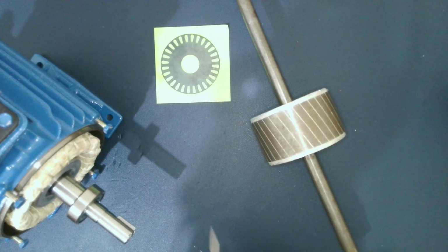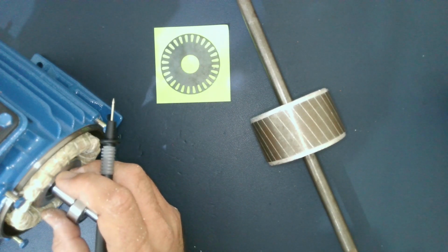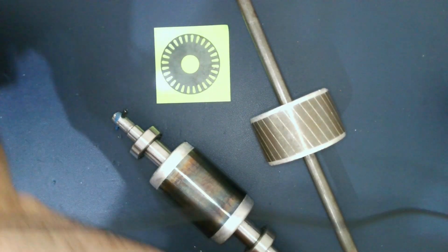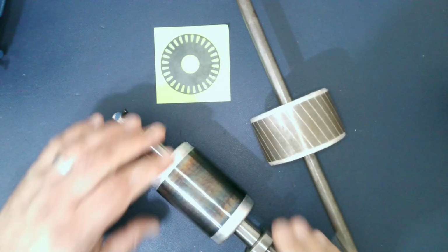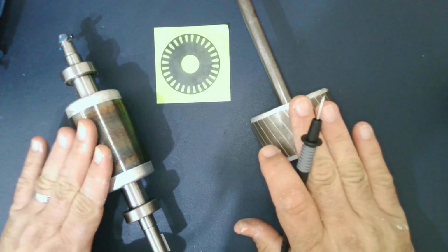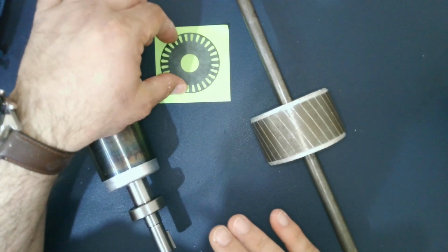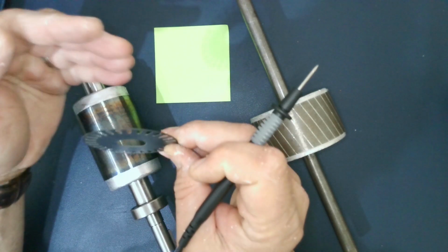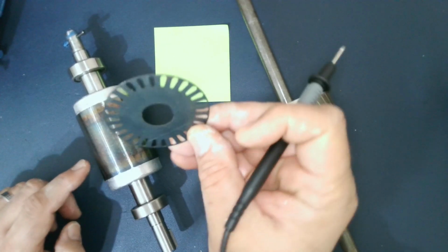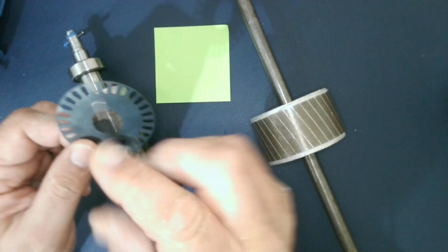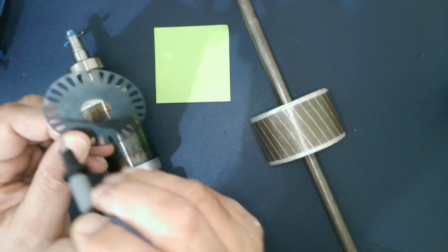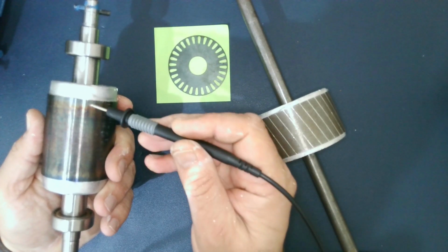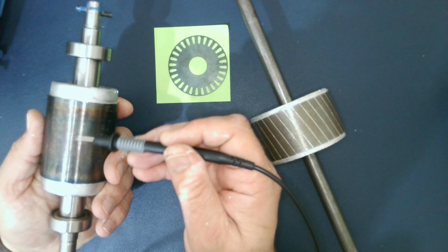Back to the real machine we have here. That machine has a stator and a rotor. I'm going to take the rotor out and move the stator aside so as not to confuse us now. So this is the rotor we have, and this is another sample of a rotor. And this is the laminated sheet steel we have. If we stack these laminated sheet steels together, they form this rotor, as we can see here. So we have the slots, and we are going to add the conductive rotor bars here. Looking at that one, we notice we didn't see any bars, but we see the laminations.